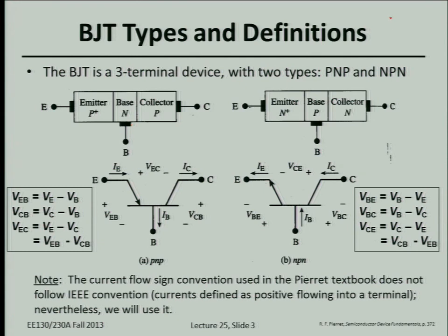Also, the structure itself, typically, if you look at a cross-section, usually the emitter is a small PN junction. So let's say a P plus region here. And then we form that by diffusing a heavily doped P-type region into an oppositely doped N-type region. And then that N-type region actually is also diffused into a P-type substrate.